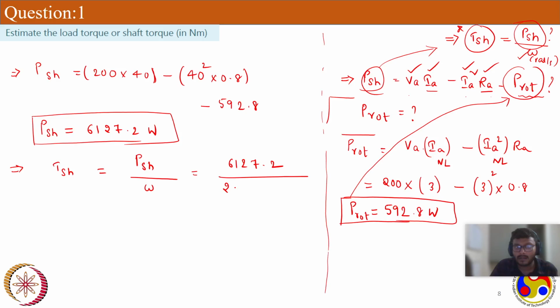And then we saw the comprehensive power flow diagram in a DC motor and how the losses are shown in a pictorial representation. So we arrive at the shaft power at the end. And then we saw the basic equivalent circuit of a DC shunt motor where our field winding and armature winding are parallel to each other having a single supply.